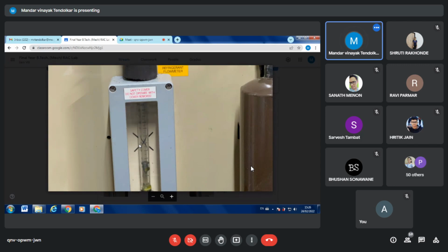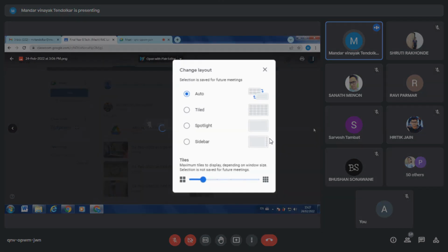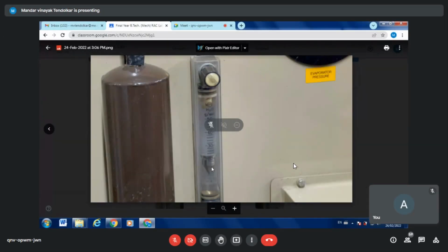This is the refrigerant flow meter. So you can see, can you read the scale? This is 6, this is 8, this is 10, this is 12, 14, 16, and like that. So we adjusted it somewhere at 5, 5 gram per second. And this is the condenser part, water cooled condenser. And then, yes, this is that water part. So you can read 20, 30, 40, 50, same.